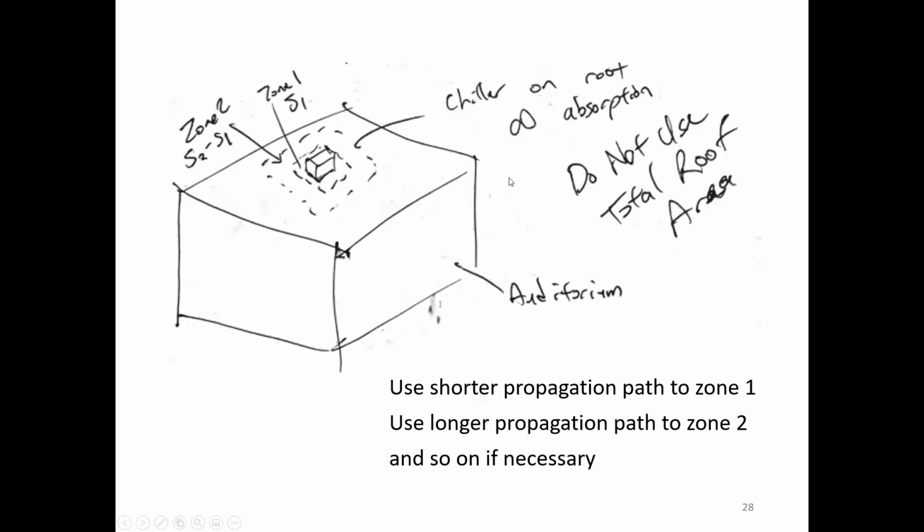If you do that, you might get, so you have a source, you have a sound pressure level out here. If you had a big enough area, you could potentially get a sound pressure level on the inside that is larger than the sound pressure level outside. You know that's not possible, right? But I've seen people make calculations like that. So you don't want to do that. Make a more reasonable approximation like this. If it's really critical, then do a finite element analysis type of thing.